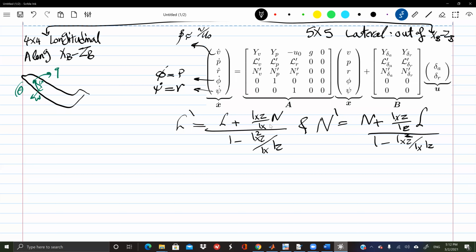So inertially, what I'm trying to say is that when I apply pure roll or pure yaw, I will get both, okay? Because they are inertially coupled. This is in addition to the aerodynamic coupling. All right, we know what are these dashes now. Let's please get them for a specific airplane to study it and see, because I want to study this system. I have a dynamical system. I want to study its stability. How can I study its stability? Any clue?